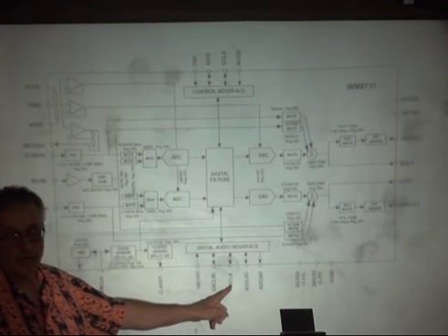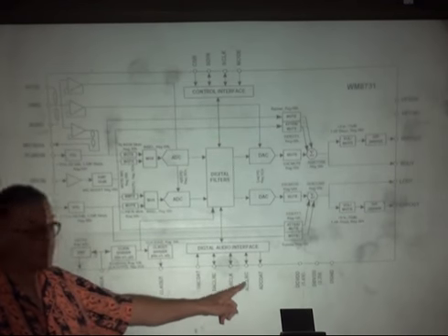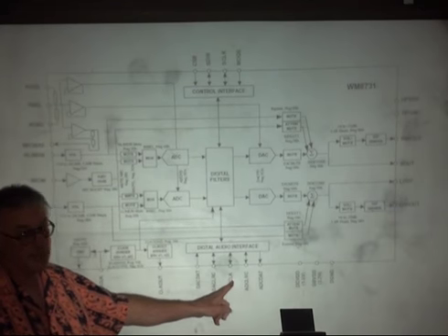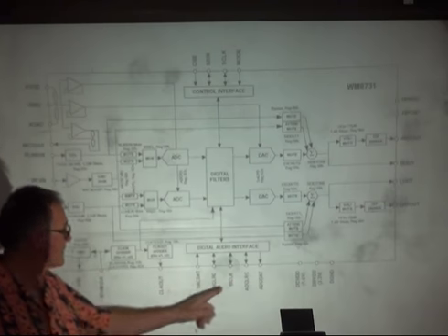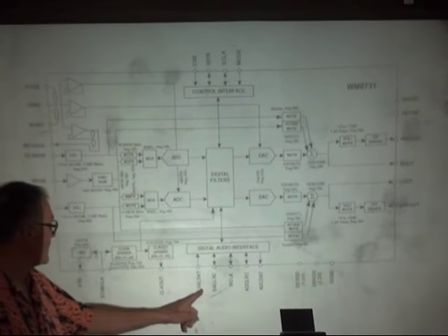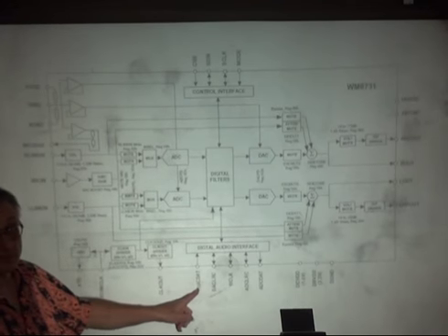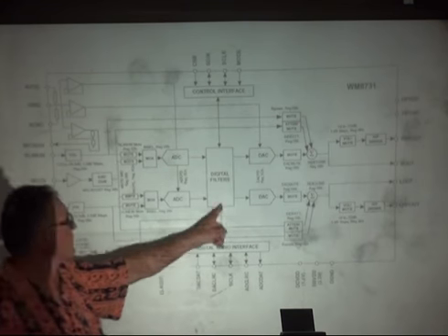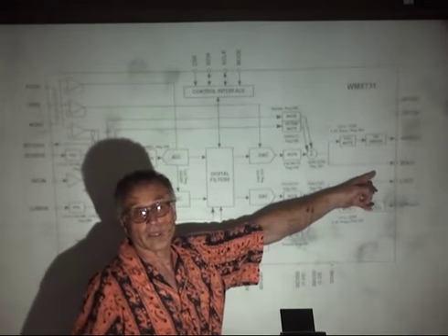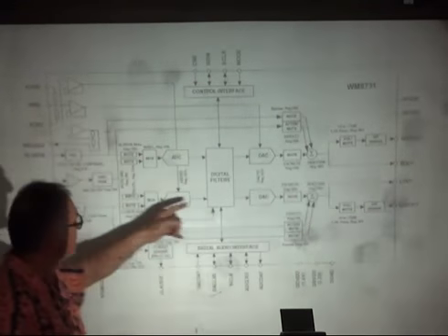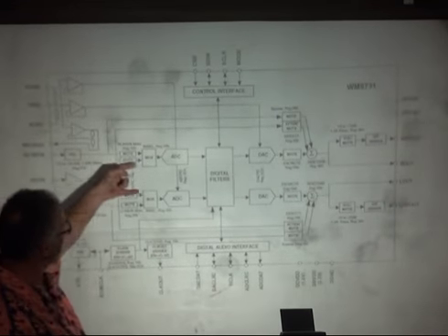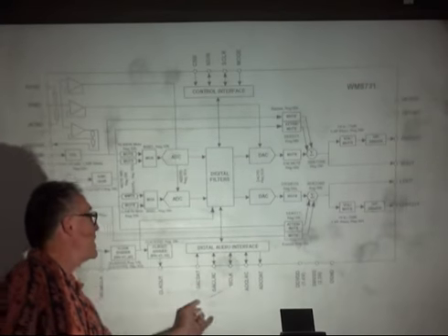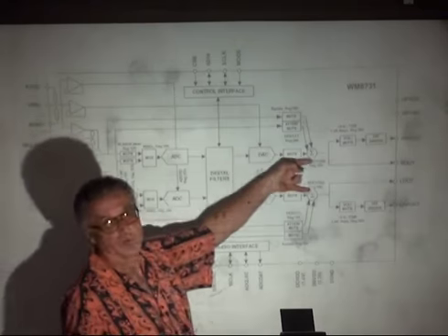There's a bit clock, which is much faster. I'll talk about in a minute. A bit clock that will synchronize the serial transfer of data. And then there's a DAC data, which is going to be generated by the FPGA and goes through the audio interface and out through the DAC to the output. So the flow of data will be our line in through the digital filters, down into the FPGA, back out of the FPGA through the digital filters through the DAC.